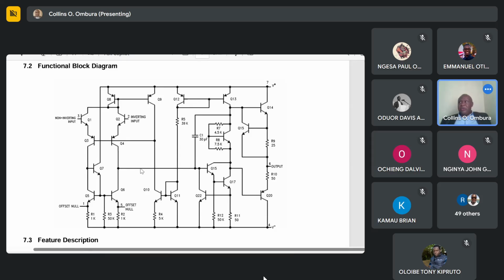Now the signal goes to the input of Q15. Now Q15, Q17 is a Darlington. Now the resistance seen looking back into the output of Q4 and Q6 is a very high impedance, because it's 1 over hoe of Q4 and Q6. So to maximize the voltage transfer, we need to load it with a high resistance. So the high resistance is obtained by using Q15, Q17.